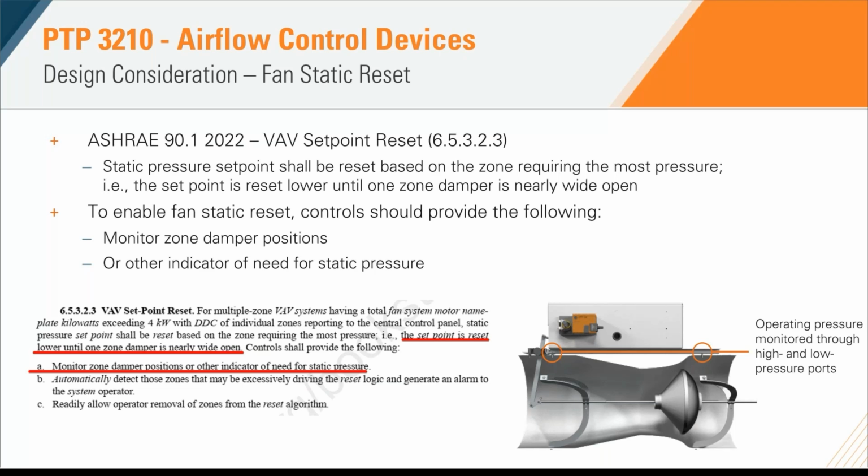Now, it is important to mention, not all Venturi valve manufacturers will provide some sort of static pressure monitoring as default. So it's always important to double check with your vendor to make sure that the option for static pressure feedback is either standard or an optional item that has to be specified.